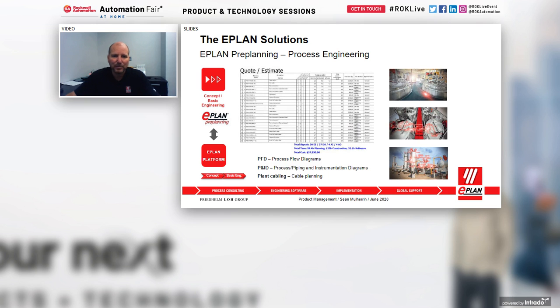And finally, Pre-planning can also be used as a quoting tool. If I design a process flow diagram or process and instrumentation diagram, I can capture the values for planning, design, construction, and also price information for each one of my objects. I can create a report identifying my signal requirements, how long it is going to take me to plan my system, how long it is going to take me to build it, and how much it's going to cost. So you can really use this tool as a quote or estimate tool right up front in the engineering process.